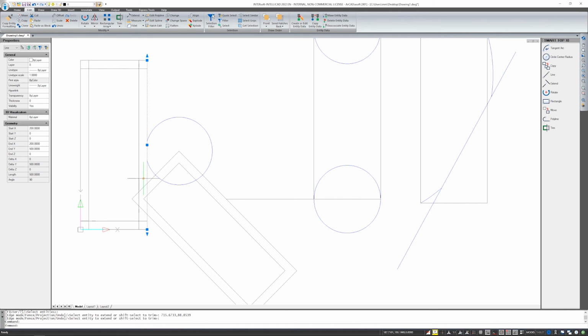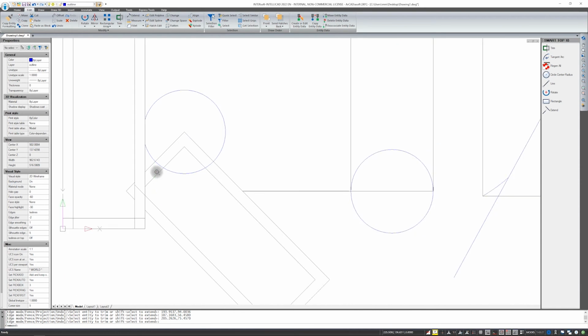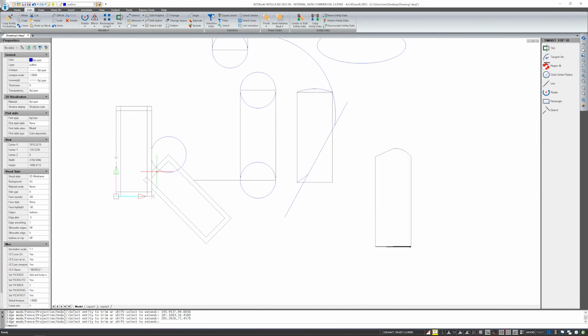When you trim, you often select more than just one element, and it will save you time selecting the option every time. So I can mark more elements here, so these elements will be cut. I will approve, and now I can cut this piece of an element. It has been completely cut out. And here I just want to extend it. So I press the Shift key and show what it can extend to. Please remember that Shift is such a button that precisely when it comes to lengthening and shortening, it works interchangeably.